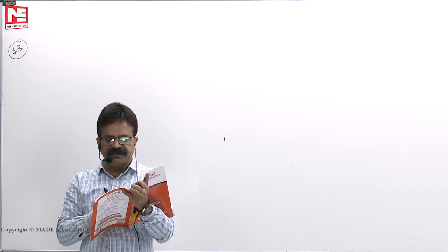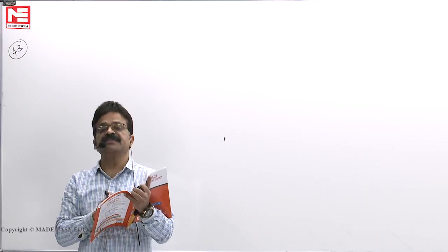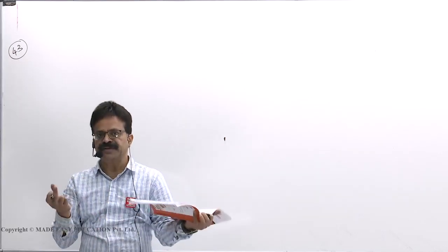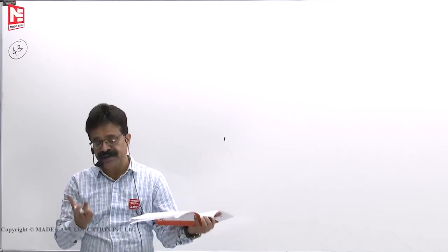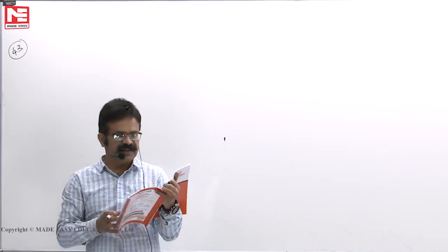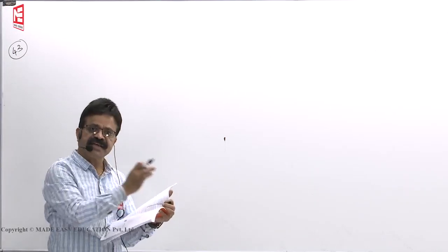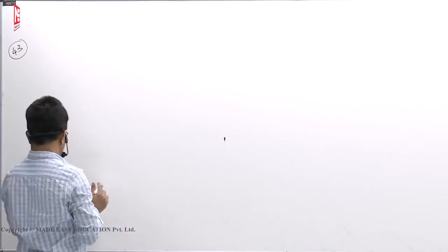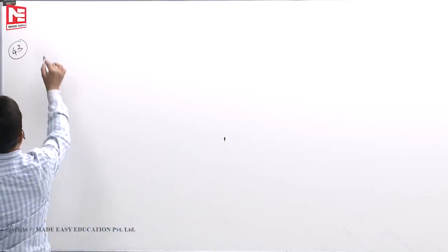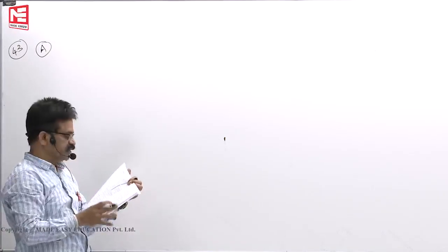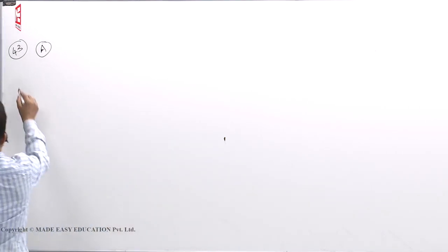It means that any arch cannot be built in the shape of theoretical arch, because the loads are moving, bending moment also changes, but the already built shape cannot change. So assertion is correct, reason is correct, and reason is the correct explanation for the assertion. So this is what I have told you. 43, assertion, reason correct, and explanation is also correct. That's why 43rd one is A.